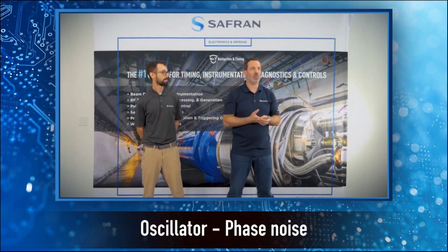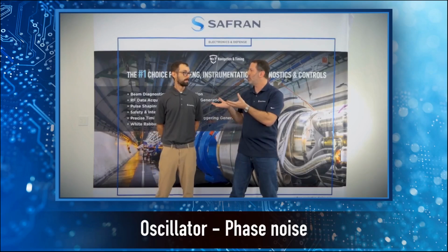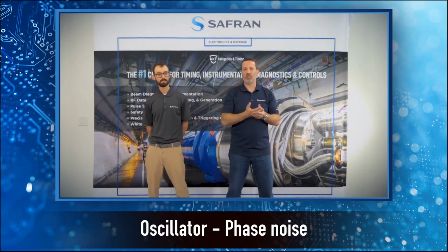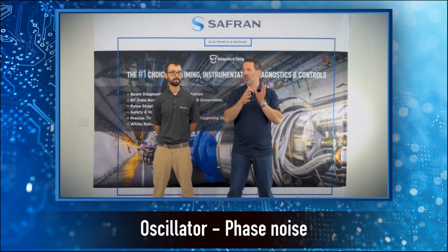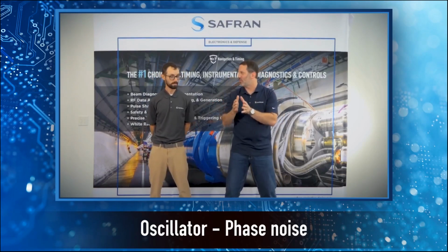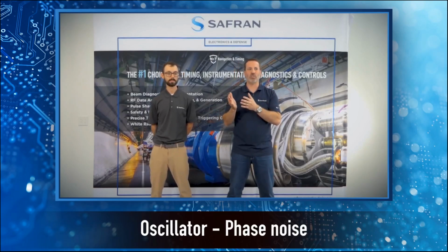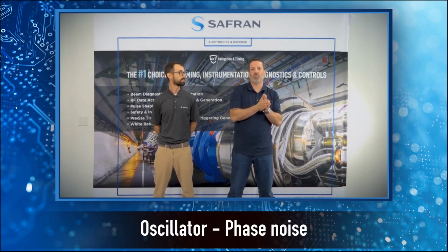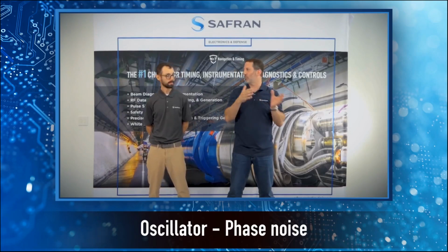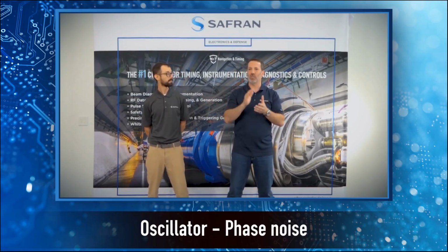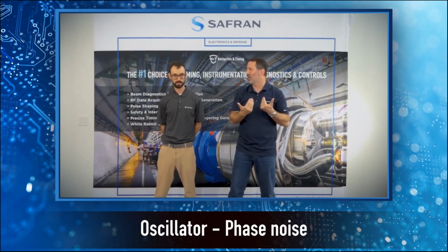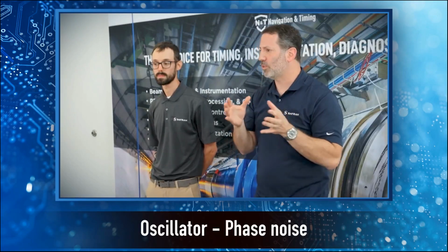That's because, except for the TCXO, generally speaking, the differences in accuracy between the OCXO, low phase noise OCXO, rubidium, low phase noise rubidium, and the options on the VersaSync are not so different while you're synchronizing to a reference. Really, the major part that affects the accuracy is the type of reference that you're synchronizing to. But holdover is really key on the oscillator selection.